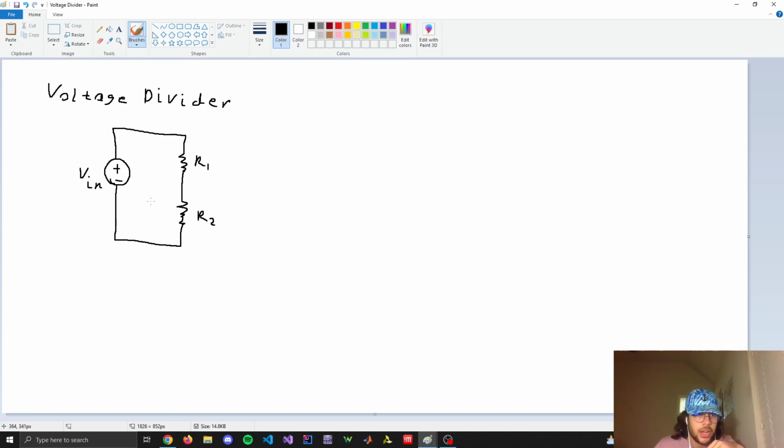So we're going to use these 2 laws to derive the equations for the voltage divider and current divider. For the voltage divider, knowing that these resistors and the voltage source are connected in series, the current I flowing in the circuit is going to stay the same. So when I write the KVL, that's going to say Vn is equal to the voltage drop across each of these 2 resistors added up, VR1 plus VR2.